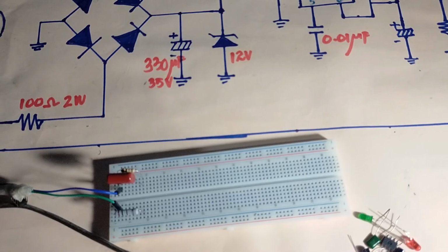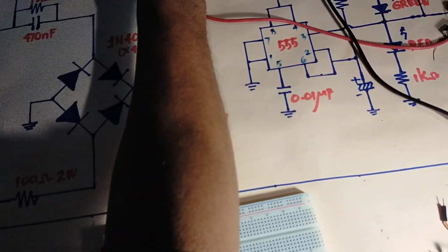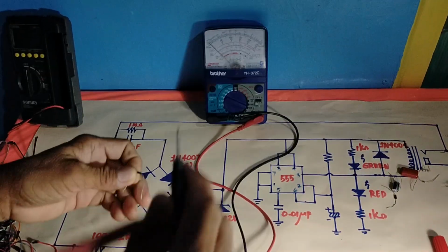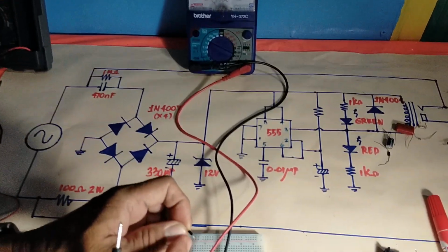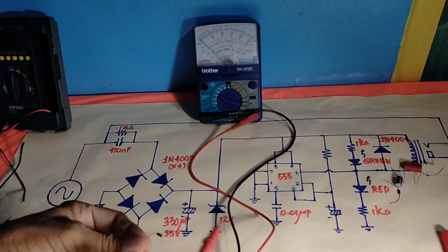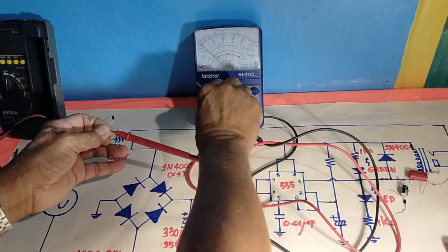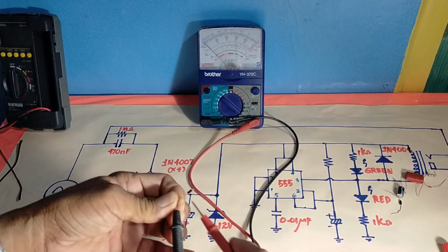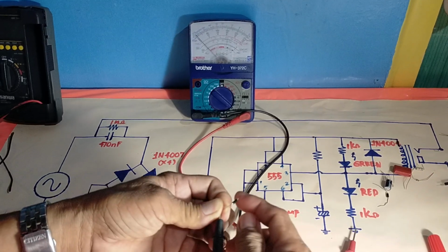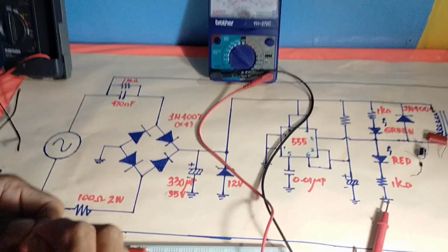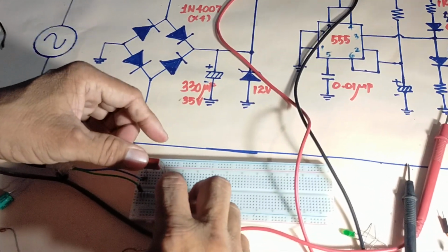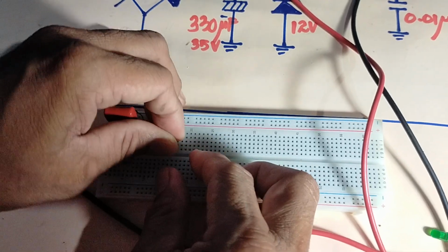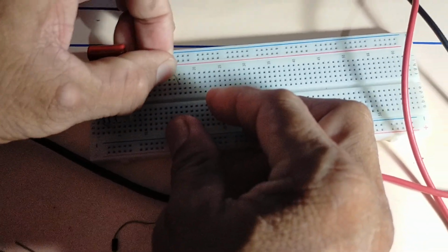Okay, we can use this tester to identify, because you cannot easily identify since the gray color band here was erased. So, this is now the cathode and this is now the anode. The anode is actually connected to these two terminals over here. Okay, it goes like that.